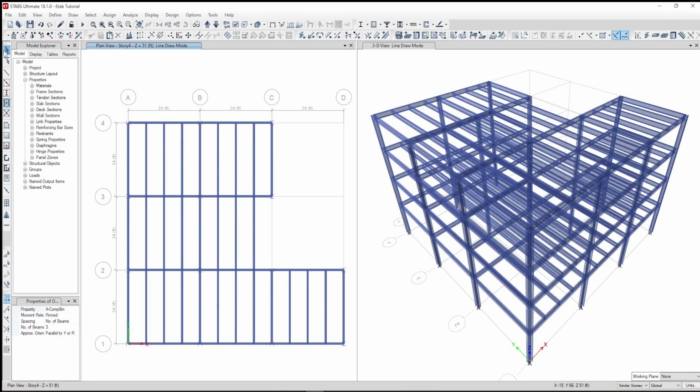To remove composite beams, use the intersecting line tool to select the beams. Left-click and draw the selection line to intersect the beams for deletion. Once your selection line intersects all objects you wish to select, double left-click to select them. Press the Delete key on your keyboard to delete them.